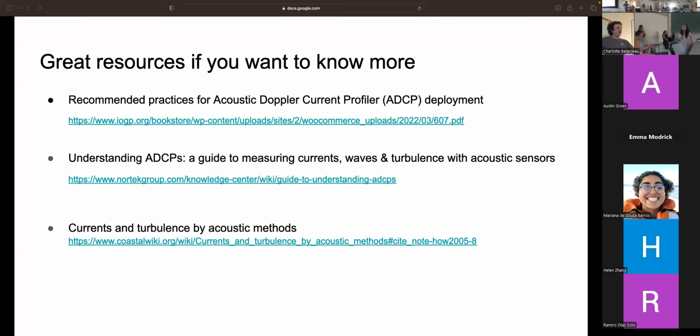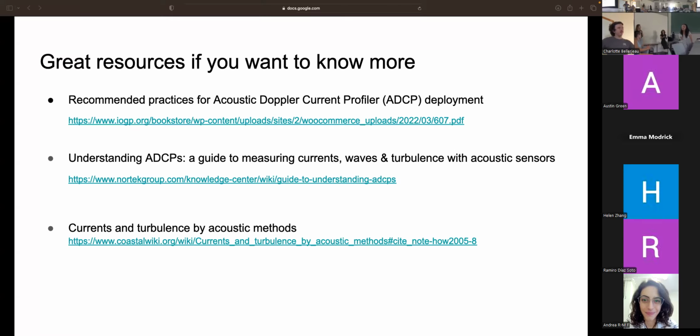The thing is, when you go back and forth on a boat, you're changing directions. The ADCP doesn't necessarily know that you've changed directions. It has a compass in it, but in the code you have to tell it that you have now changed directions, because it thinks the currents have flipped direction since you're now going the other way. The ships already have all that set up, so you don't have to worry about it. When you do it yourself, that ends up being one of the biggest frustrations.